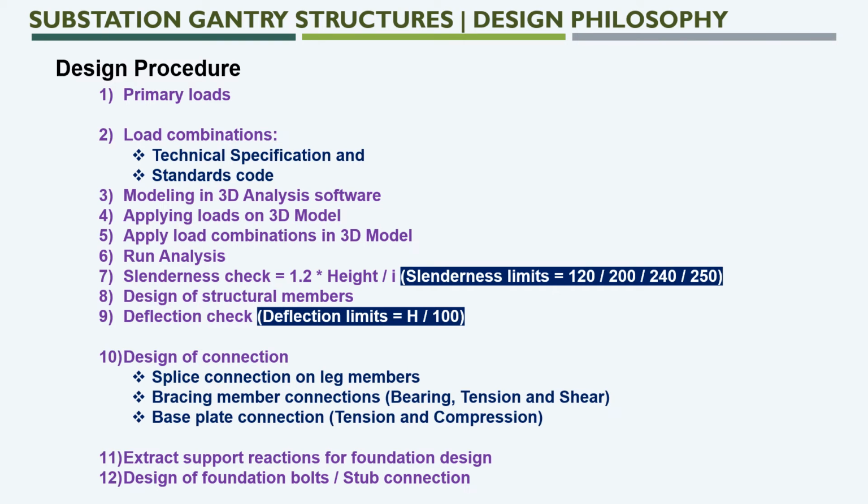So what do primary bracing and secondary bracing mean? Primary bracing will take both the tension and compression loads and transfer them to the main leg. But the secondary bracing will not take most of the load from the structure distribution. It will act like a redundant member.